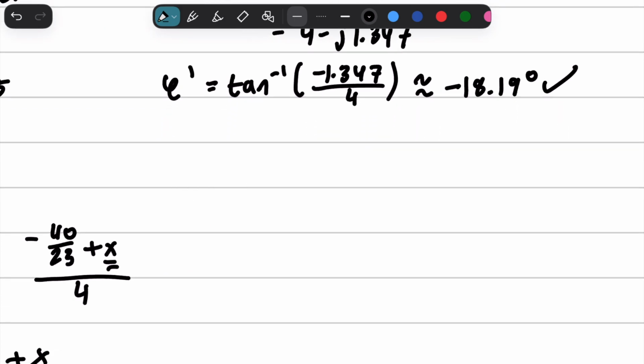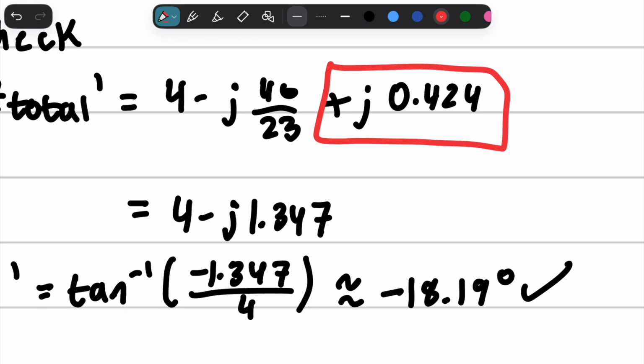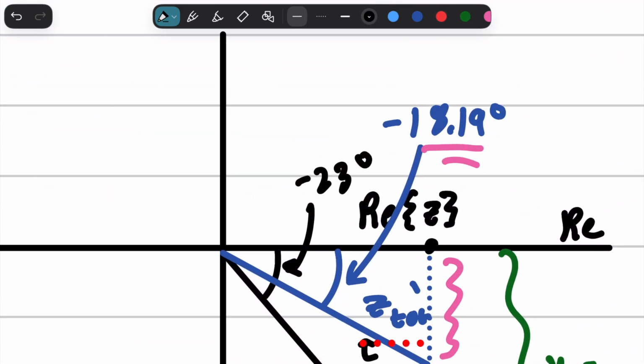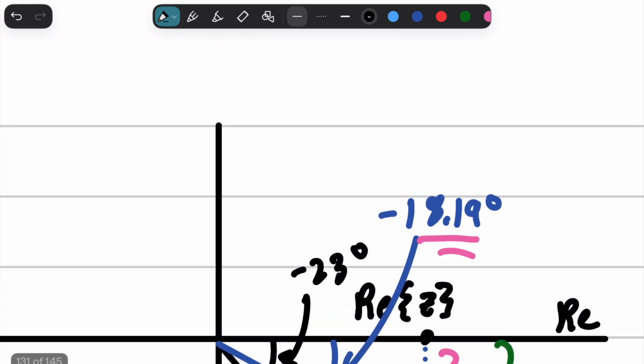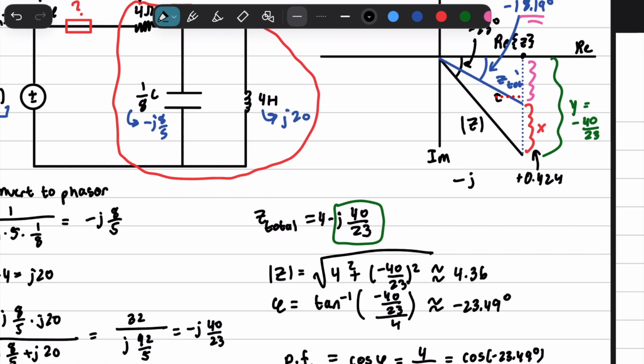or, well, you know what I'm talking about, step 5, and that's actually to find the component. Now, when we see what we're adding, you can add a capacitor, you can add an inductor or something like that, but we want to find the simplest thing that we can add. And naturally, we've seen that inductors are typically within the frequency domain look like a positive j, and a capacitor typically looks like a negative j, right?